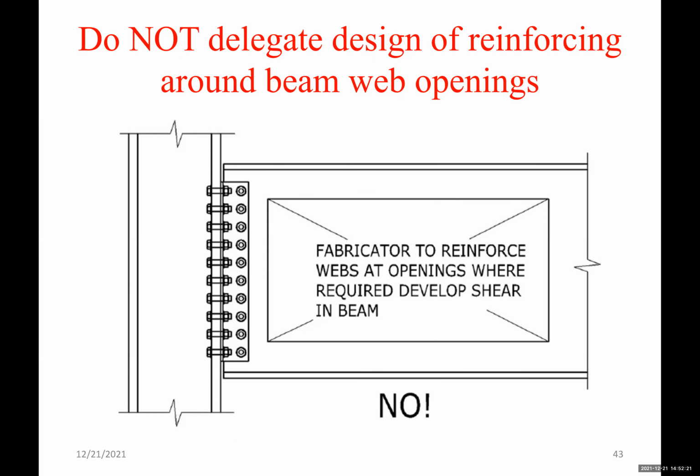Do not delegate design of reinforcing around beam webs to fabricators, such as asking the fabricator to reinforce webs at openings where required to develop shear in the beam, okay? This is not the responsibility of the fabricator. You design the beam as a structural engineer, and if you have something like this, then you have to design the reinforcing. Even if you provide the forces, of course, the reactions and everything to the fabricator, you need to do that.